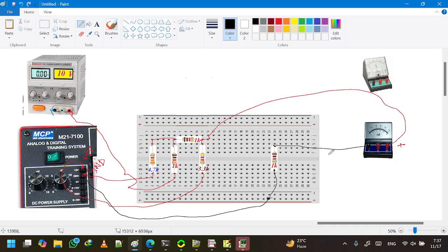We have most of the things. Now we will have the load current IL. So this IL will be 3.260 milliampere. After that, we will disconnect this resistor. So if we do not want to disconnect it, we can just replace it. But for better understanding, let us disconnect the load and draw a short circuit. Now instead of IL, this one will give you ISC, or short circuit current.